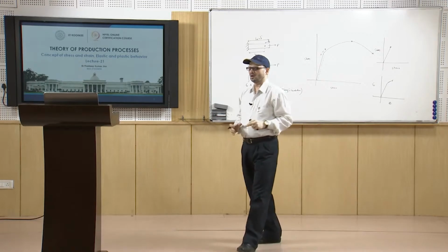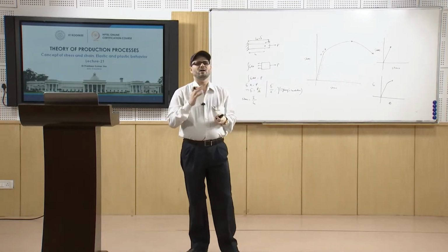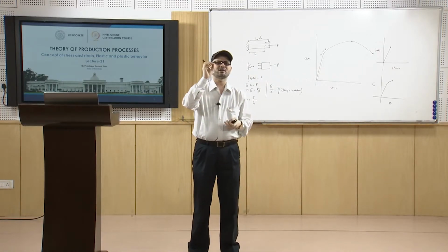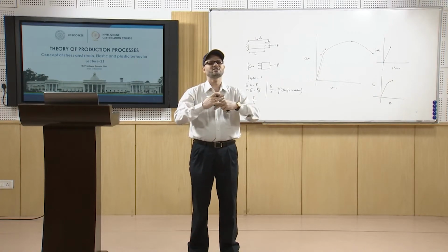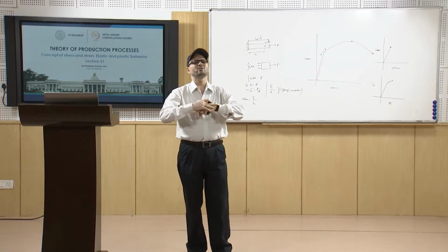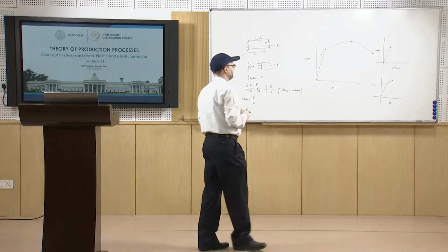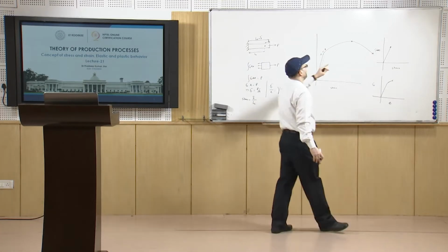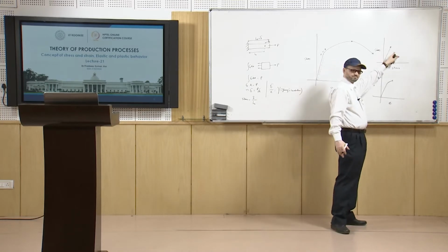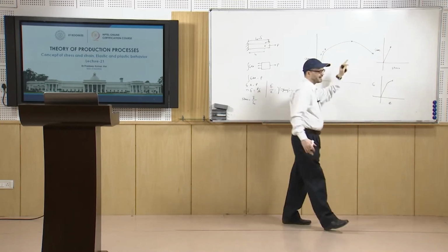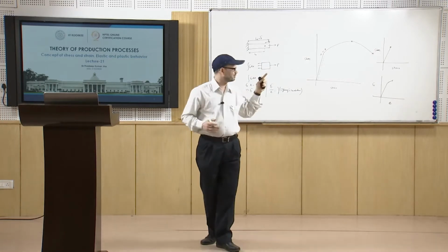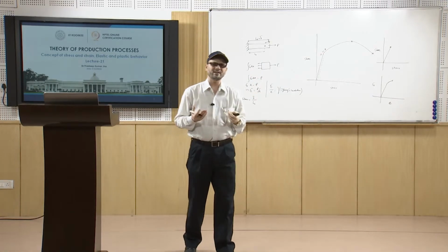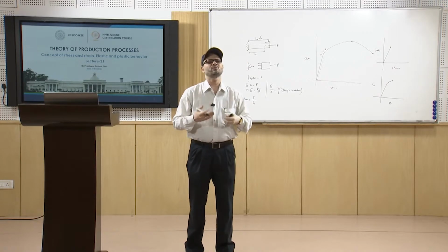But the thing is that many a times, in the case of pure brittle materials, the cracks which generate basically then spread over the area, and then without any indication you get this fracture. Now, in the ductile case you have appreciable deformation; it is not desirable to have such kind of fracture, because it does not give any indication of when the fracture will occur.